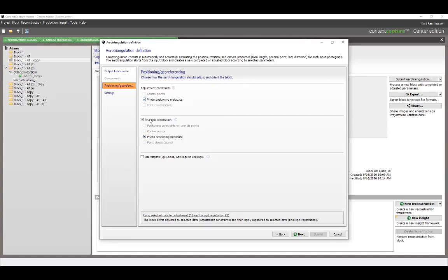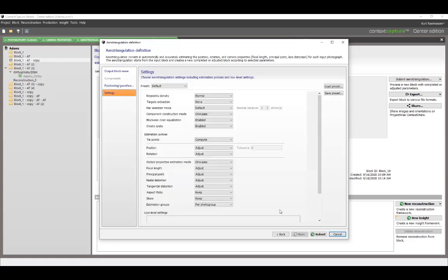Now, typically with an RTK drone, you're probably going to want to throw down 3 or 4 control points and really just use one of them to lock in your vertical elevation and use the other ones as checkpoints. I'm actually in a couple weeks going to be doing, either me or my colleague, an RTK presentation that we'll go deeper into. But these are some of the settings that are important when you're doing this. And then we say next. Now, at this point, we just want to hold everything that we have here and say submit.